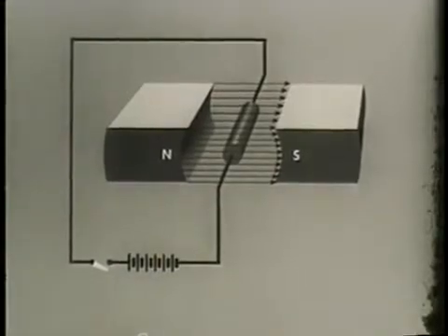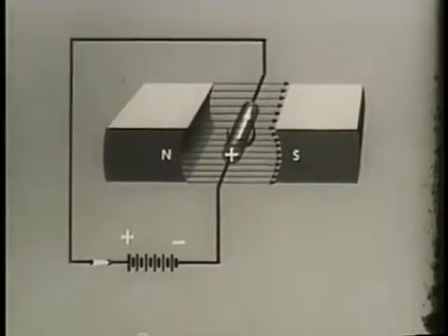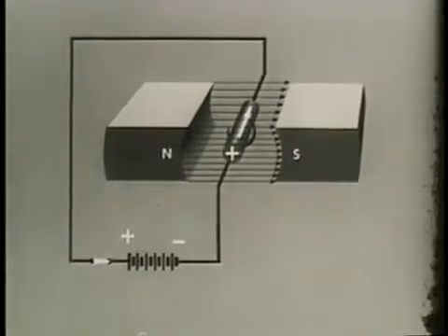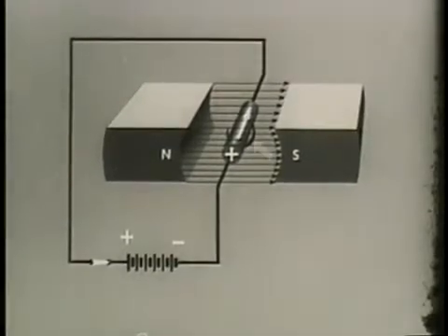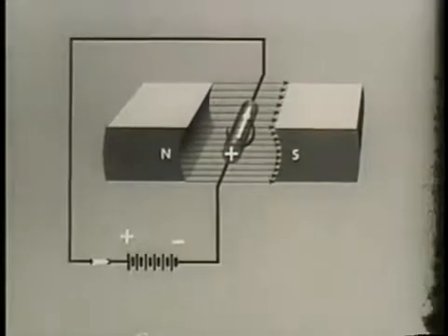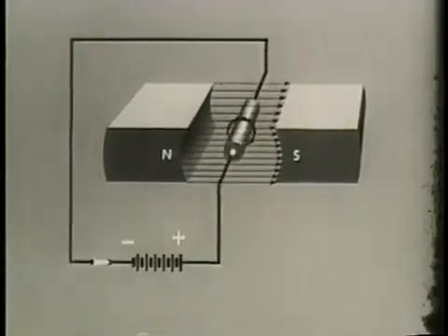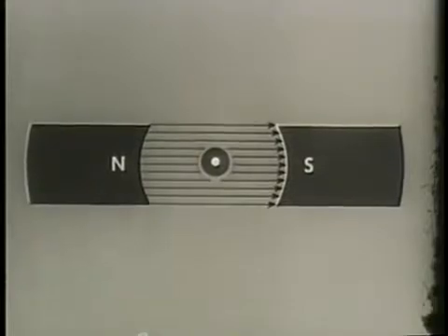To see what really happens, let's go to a drawing again. Here, a conductor is suspended in a magnetic field. Current flow from a power source creates its own magnetic field in and around the conductor. This field around the conductor reacts with the main magnetic field to cause motion of the conductor either out of the field or into it. The arrow point indicates the direction of the current flow in the conductor. In this case, the flow is toward us.